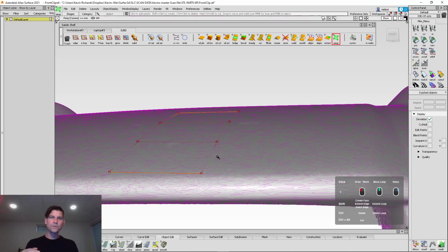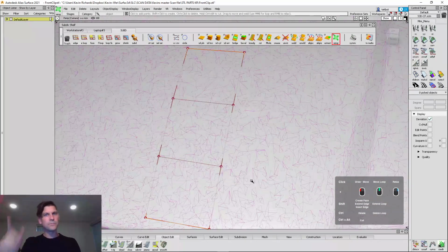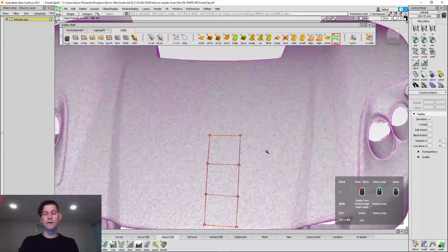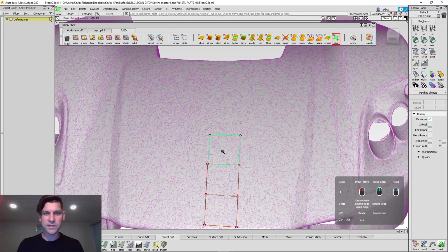And this is really cool, but do note, the underlying subdiv surface, unless you have a lot of topology, a lot of points, is going to be slightly below the surface or above, depending on the condition. So it's not basically matching or rebuilding the scan per se with the limit surface, but just the cage, the actual points. That's something just to be aware of, and hopefully there's something that can be done in the future. I could see an offset or something from that to be able to get it much closer.